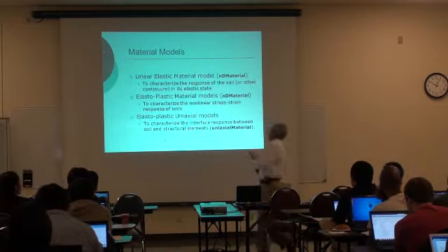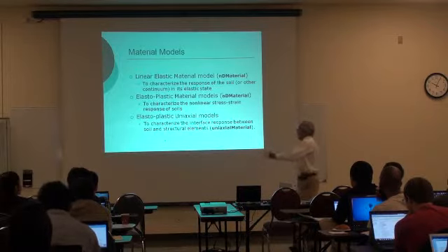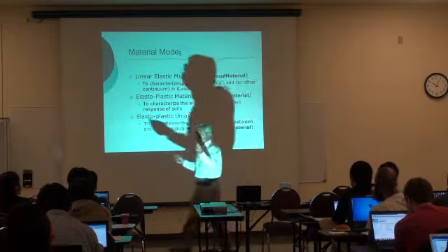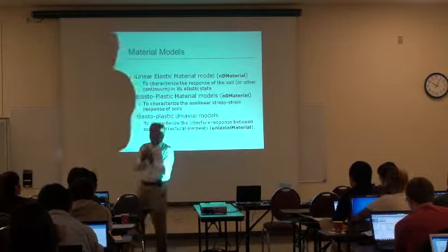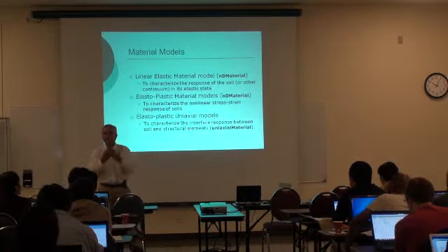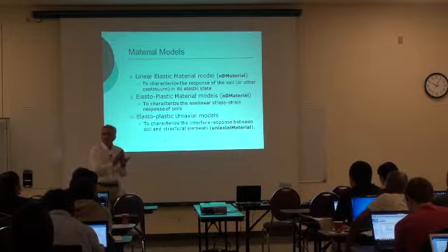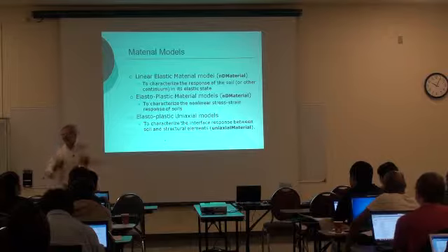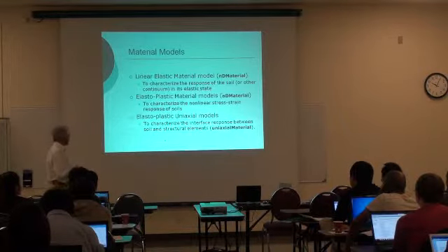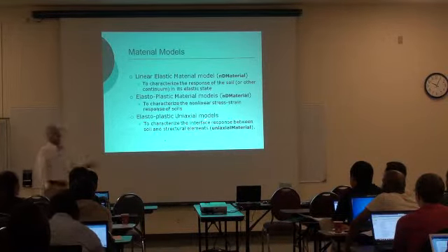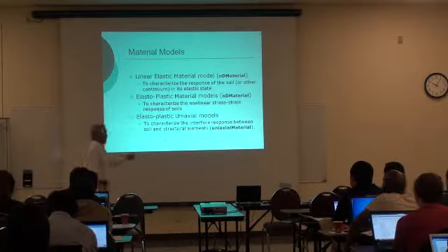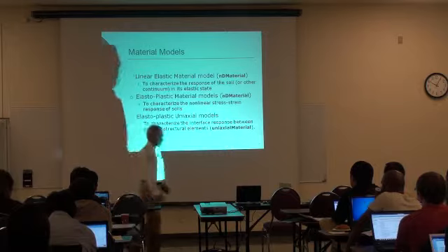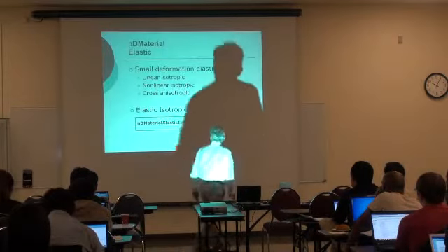And also, in some cases, when we are trying to connect piles and soils, in practice it has been very common to use springs. And these springs really characterize the nonlinear response between the soil and the structure. And they are usually given names like PY curves or TZ curves, QZ curves. So OpenSees has uniaxial material models that allow us to characterize the interface response between the soil and the structural element. Okay. So they are there.